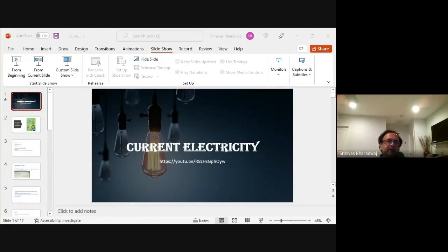Okay, so this is a very typical example. Right here you have this one and this one in parallel. R2 R3 divided by R2 plus R3. Take that and replace this one with the equivalent resistance. There's 2 and 3, therefore 2 times 3 by 2 plus 3, 6 by 5, replace with the equivalent resistance. Okay, so you can do a quick calculation.